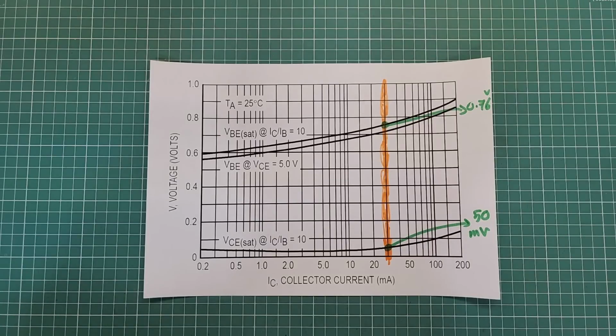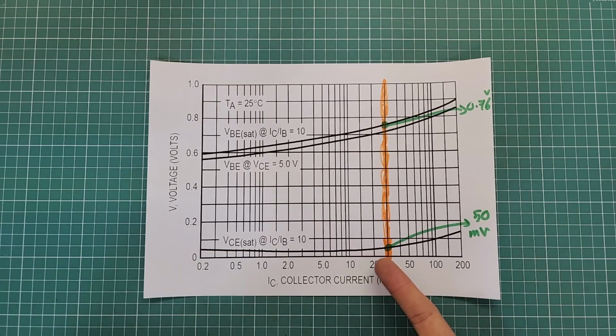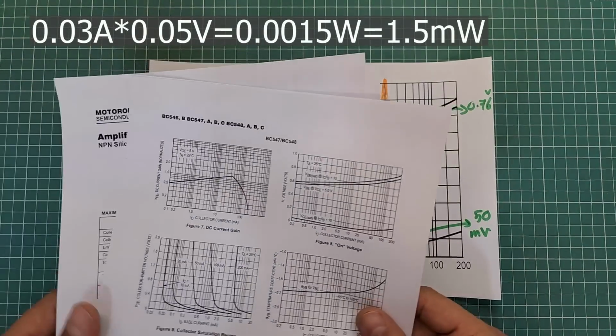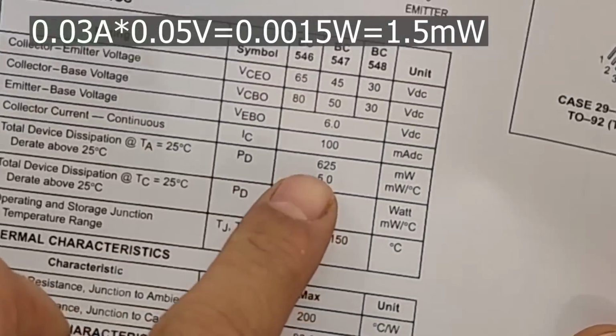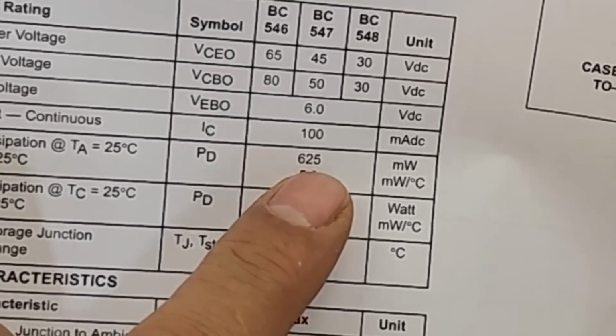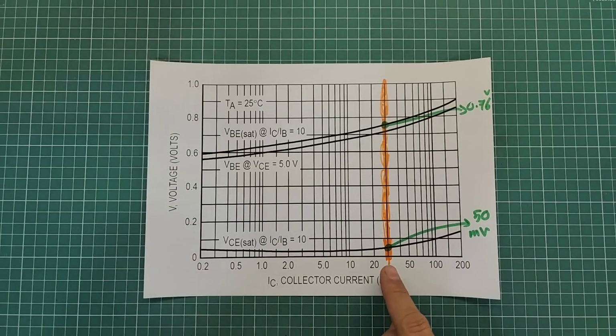The voltage across collector emitter junction of the transistor at this point is about 50 millivolts. So the power dissipated by the transistor at this point will be something around 50 milliwatts, which is far less than the maximum power dissipation of the transistor, which is 625 milliwatts. Look here. So it's safe for the transistor to operate at this point.